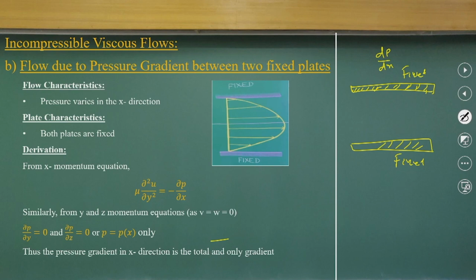That part we are looking at for incompressible and viscous flow, with rho and mu constant, and the same coordinate system, with x, y, minus h and plus h. We try to solve for the velocity field. In this case both plates are fixed and the flow happens due to the pressure gradient. What should be the velocity field?